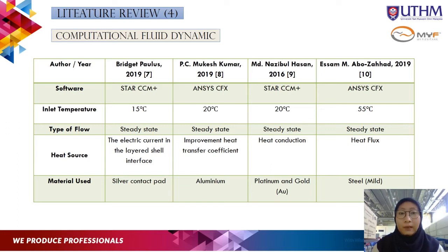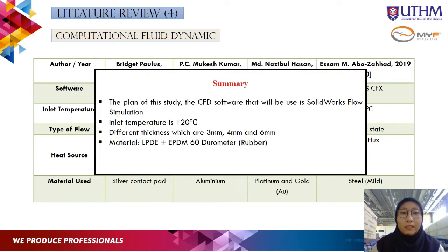So for the summary of this literature review, the plan of the study: the CFD software that we use is SolidWorks Flow Simulation. The inlet temperature is 120 degrees Celsius and the different thicknesses are 3 mm, 4 mm, and 6 mm. For the material we use LDPE with EPDM 60 durometer rubber.